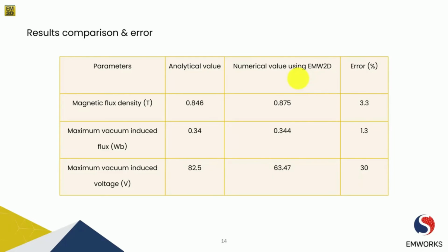Then next we have the magnet flux linkage at no load condition, where we have 1.3% error. And then finally we have the back EMF voltage, and of course based on the material types and the core material we get error, and it's huge. So we now need to optimize our geometry using our FEA tool so that we get our desired results.